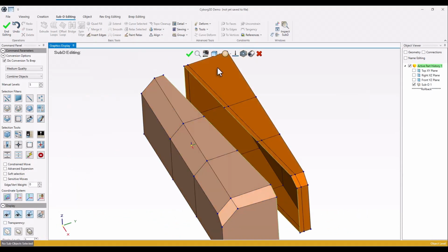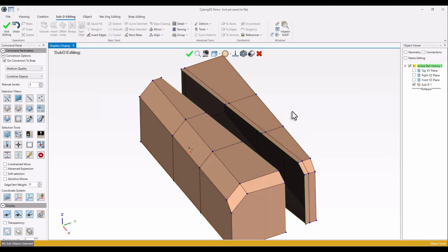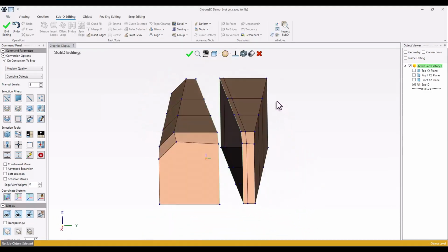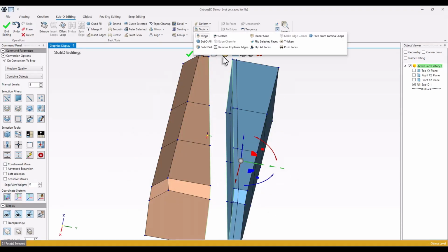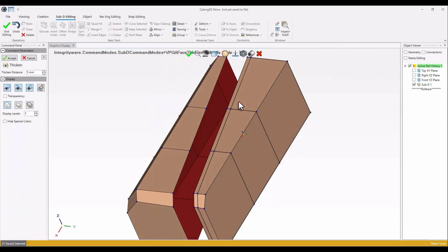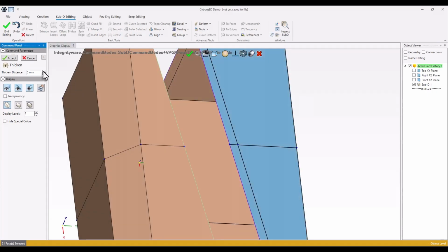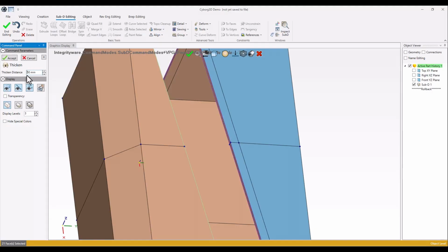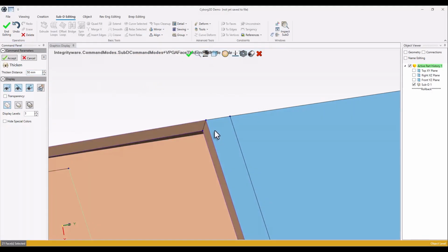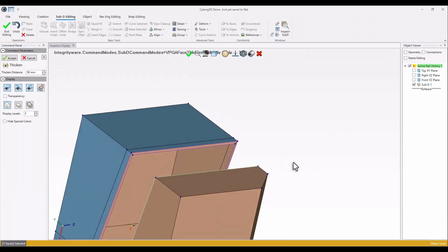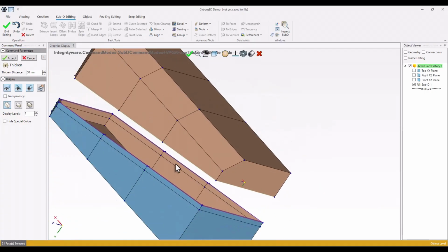Right now, in this case here, I could also make these solids. So in tools, we have something like thickness. I can go thickness this part right here once I select it, and the distance is from here. I can increase it. Probably this part is very big, so maybe 50 millimeters. So you can see the thickness here, and this is essentially now a solid one.